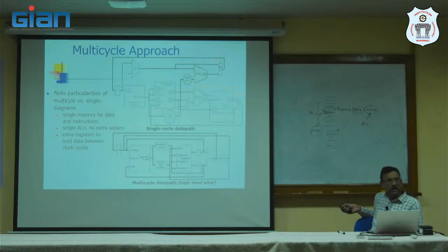That ALU itself can be used to solve these address calculations as well as arithmetic calculations in multi-cycle operations. Okay, that is the advantage of the multi-cycle data path approach compared to the single cycle data path approach. So duplication of the components can be eliminated and we efficiently utilize all the components. All instructions will be executed in equal length of clock cycle, because the instruction execution is broken down into small components, and each operation will be done in one cycle.